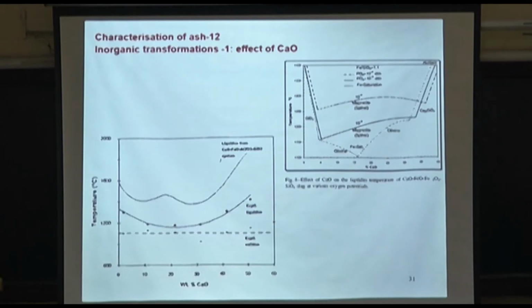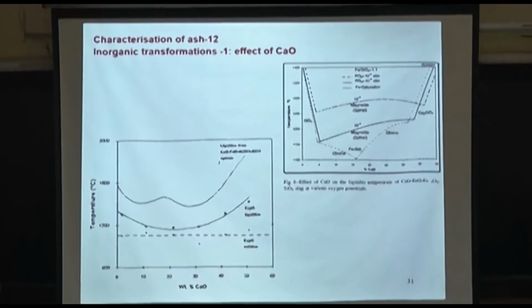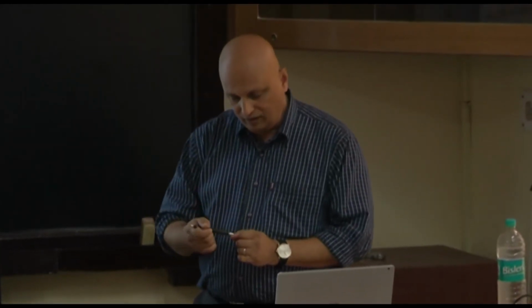So she deliberately took large particles, about 6 millimeter, 8 millimeter, etc., and inserted very fine thermocouples inside, platinum rhodium ones, because these can be very, very thin. The K-type thermocouples are not all that thin, so you can't enter. And then she measured the center temperature against the gas temperature, which is on the surface of it. That student was not the first one doing it. Before that, others have also done it.